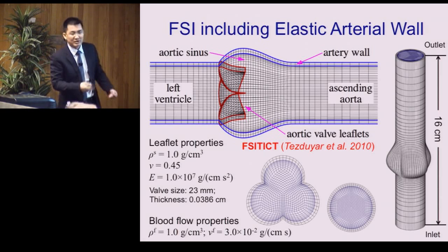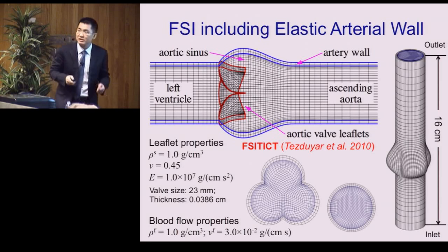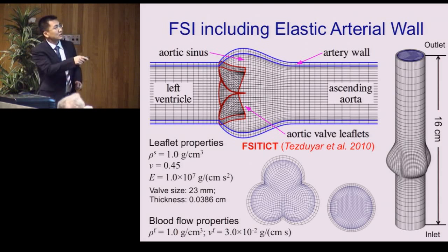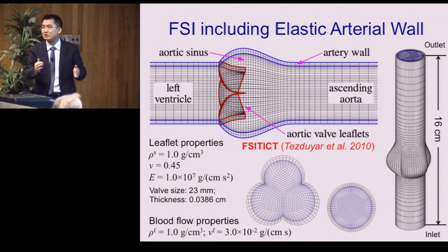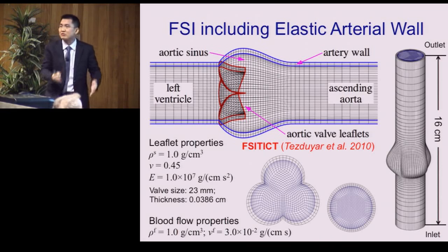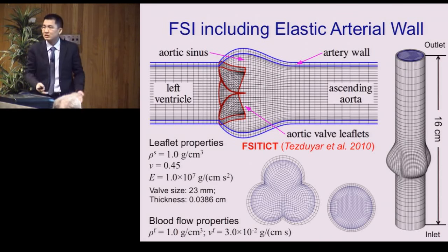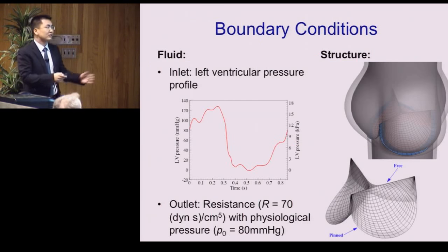Okay, and in fact this methodology makes it really easy to couple the non-boundary fitted approach with a boundary fitted approach for fluid structure interaction. Because if you look at the formulation, it doesn't really differentiate whether you have a boundary fitted or non-boundary fitted or immersed formulation. Okay, so just a very typical simulation.